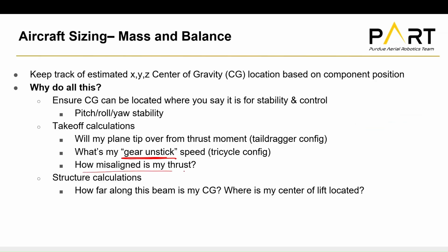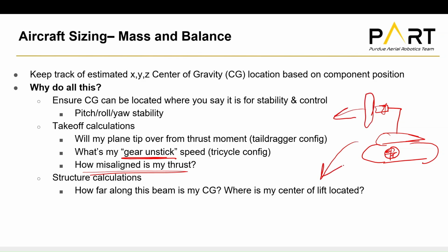You also want to look at if your thrust is misaligned off your center of gravity. Okay, so if you built a plane where your center of gravity is here, right, and this is kind of your fuselage, and you had a motor for some ungodly reason on a stick above your plane, right? Every time you accelerate, am I going to pitch my nose into the ground, right? That's another worry you have to think about as well.